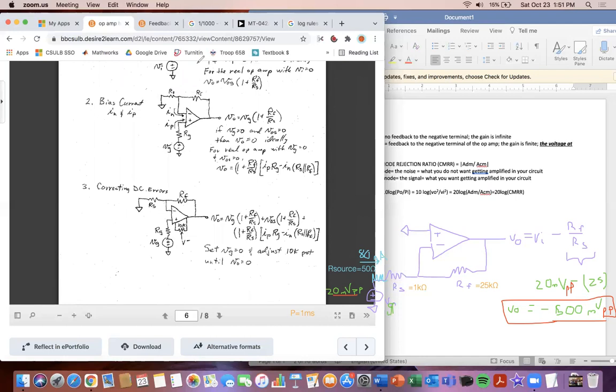What we're going to have is our normal inverting amp. So this equation here will have to be modified for an inverting amp, but we'll use this one since we have a voltage generated. And we don't have a voltage offset, but we do have a source resistor, which will have an input bias current. So we have to use these two equations. But remember, these equations were for a non-inverting amp here. So we just have to adjust it.